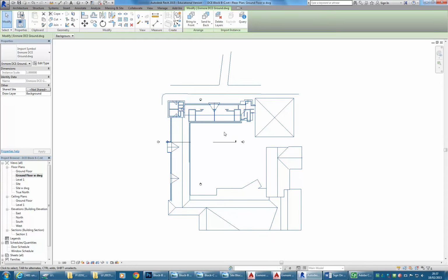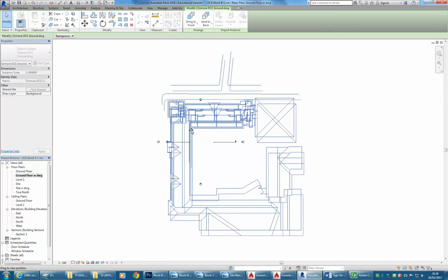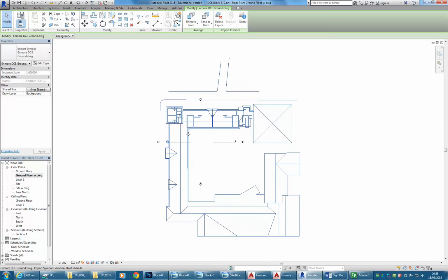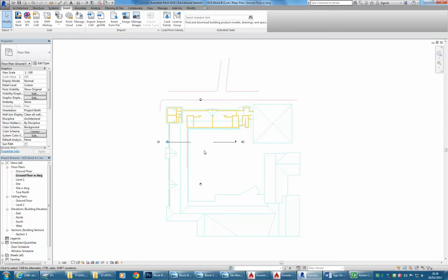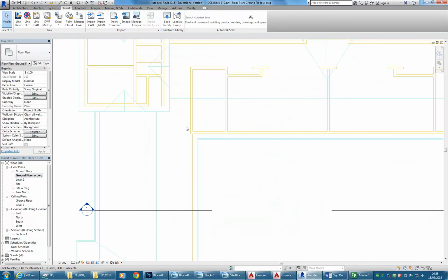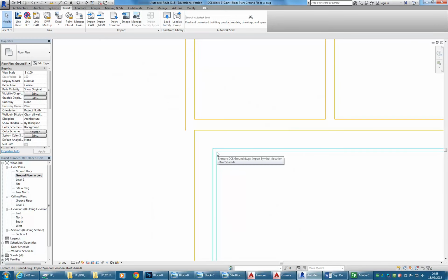And so if you have a look at those arrows, they're your elevation views, and it's good to make use of their initial position. We'll still need to adjust them a little bit, but I'm going to try and use their position as much as I can. So I'll move this down a little bit more, and so that way at least these elevations, the three at the top, are going to be useful. This bottom one will maybe need to move, but that's okay.